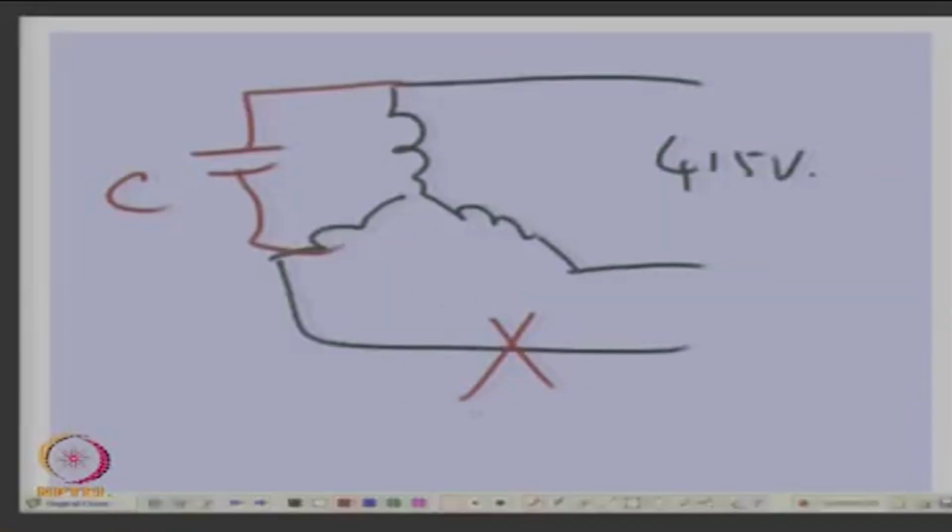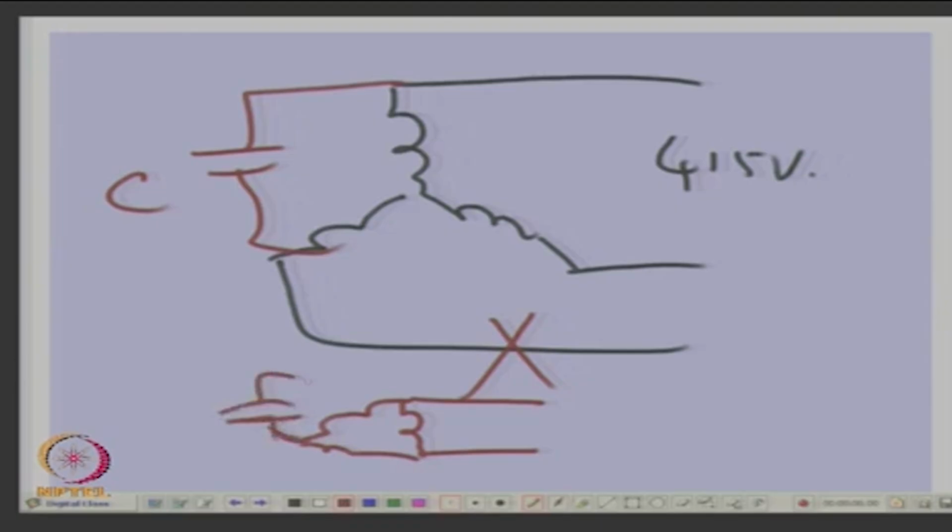You want to take one of the available motors. So, what should you do? One way is to ask the fellow making the motors to rewind it. Otherwise, if it is a star connected machine, you can connect the same thing in delta. If this star connected machine is connected in delta, what will be the rated voltage here?